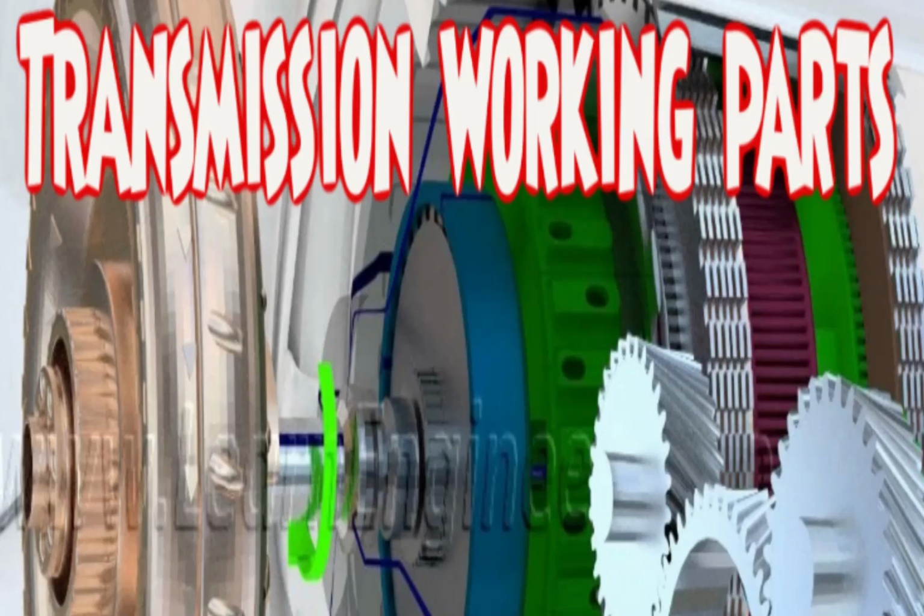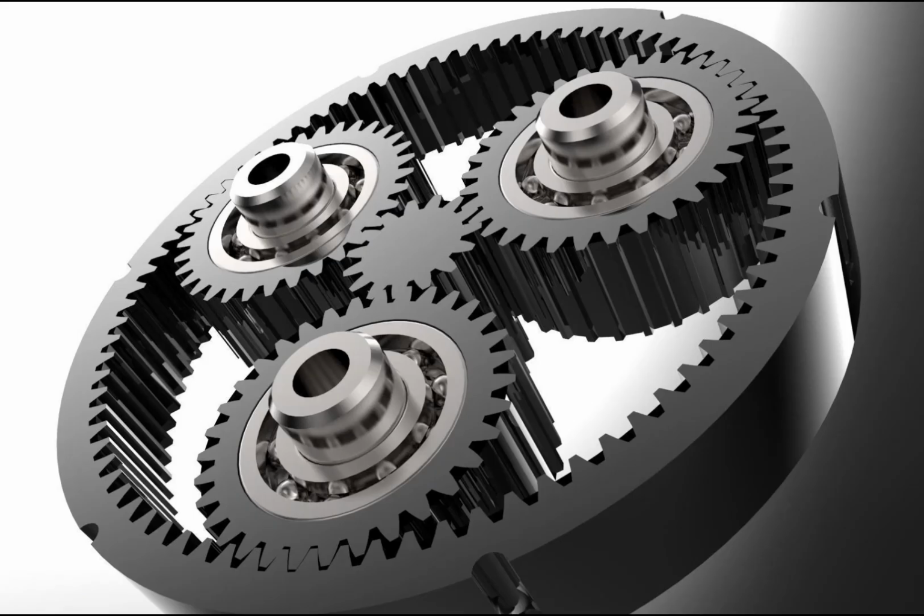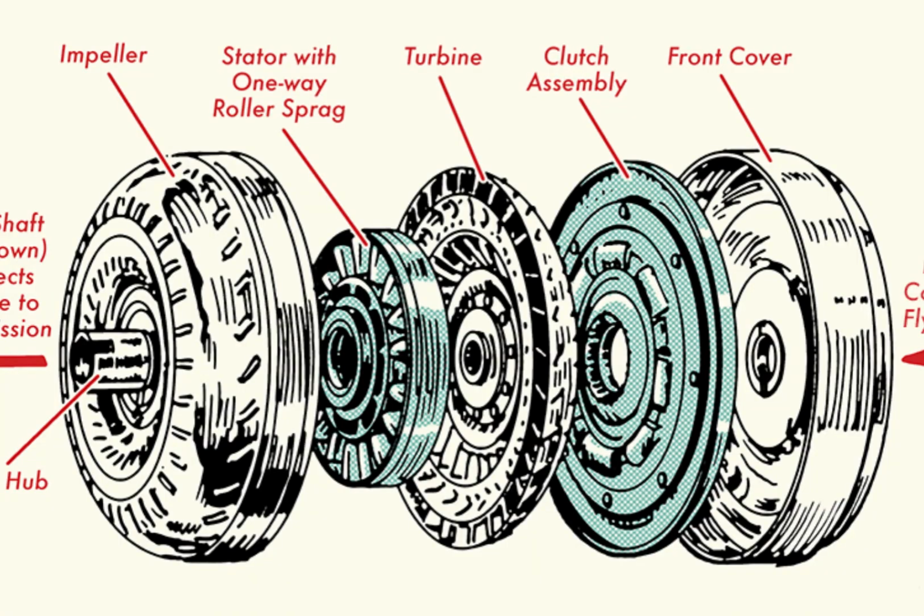How automatic gear shifting works. The transmission uses sensors to monitor vehicle speed, engine RPM, and throttle position. Based on this data, the hydraulic system activates specific clutches and bands to select the appropriate gear in the planetary gear set. The torque converter accommodates changes in speed, ensuring smooth and efficient gear shifts without interrupting power flow.